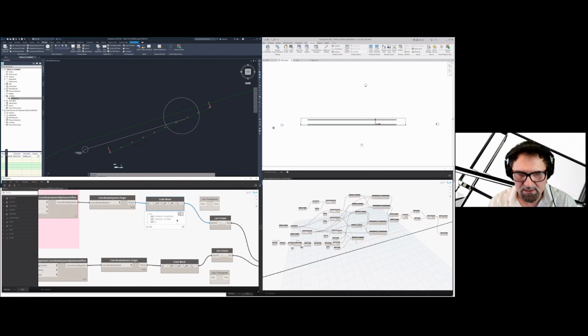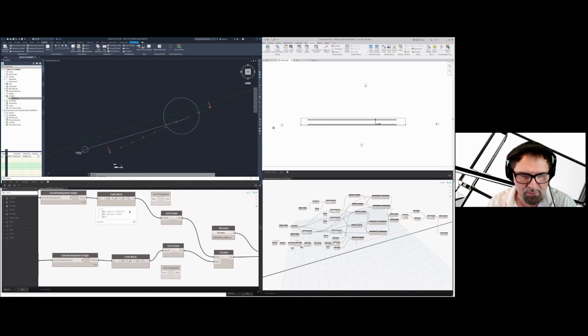Over here, you can see that those are written in a state plane coordinate system, which is another note. If you are working with the state plane coordinate system, you want to tell Dynamo to do the geometry scaling, so you're going to extra large. It will throw you an error otherwise, telling you that by default, it's not set up to handle such coordinates with such large numbers. So that's one thing that you had to do before getting to this point.